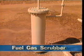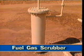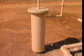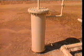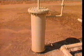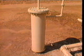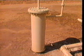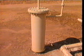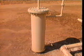The fuel gas scrubber prevents entrained liquids from passing into the burner along with the fuel gas. Should the scrubber become filled with liquid, a float rises and shuts off a valve. This stops the flow of gas to the burner, preventing the possibility of an uncontrolled fire. A drain valve is fitted to the scrubber to remove collected liquids. The pumper should check and drain the scrubber every day.